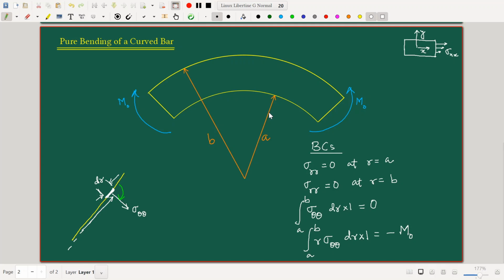Now, when we had discussed in our previous video the considerations of cases involving such holes, there can be very many different cases, and we had gone on to take the particular case of a not equal to 0 and b equal to 0. But now for this current problem of the pure bending of a curved bar, we don't have to make any such a priori assumptions. What we can do is keep the a, b, c unknown as they are.